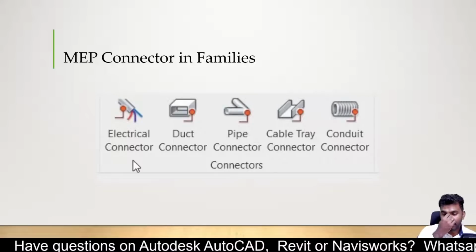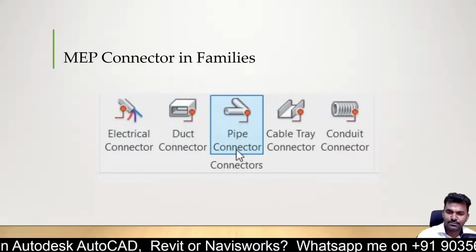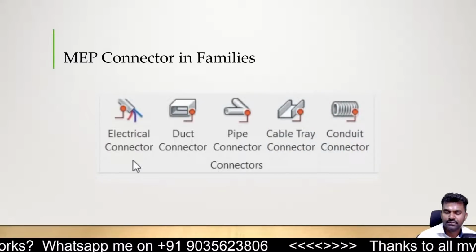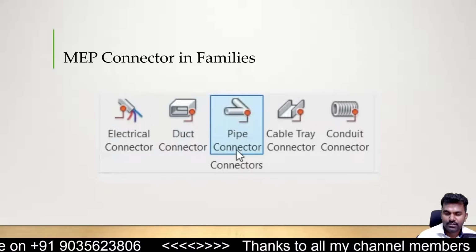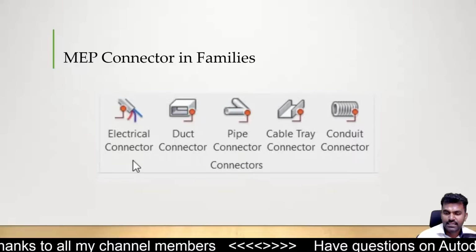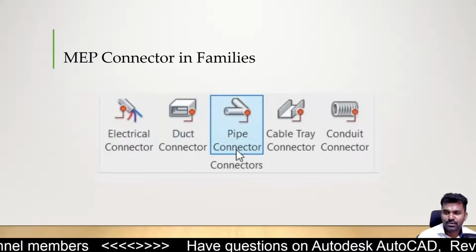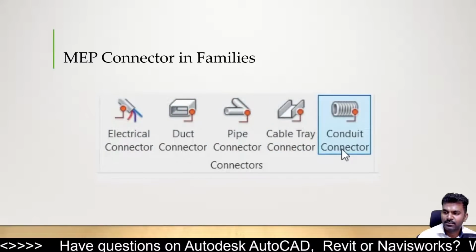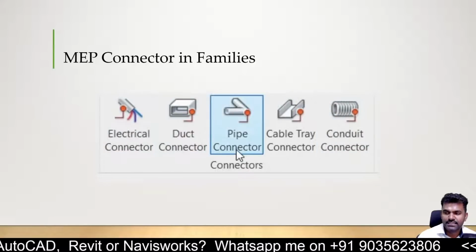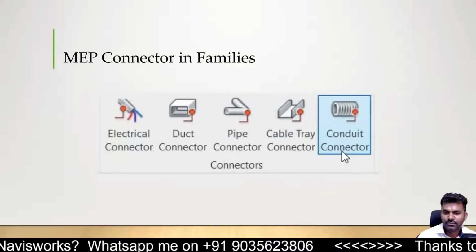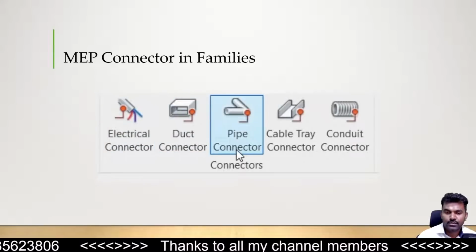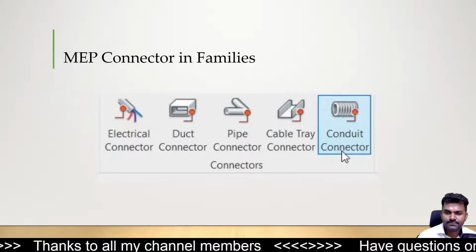MEP connectors are easy to add, just pick and place, but it's important to understand the functionality of these connectors. For architects and structural technicians, this is not so important, but if you understand the logic, that's going to make your modeling easier. For example, if you want to add a pipe connector to your water tank, you can do that with the MEP connector.